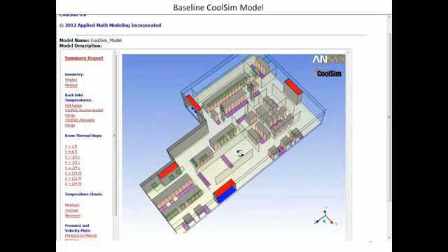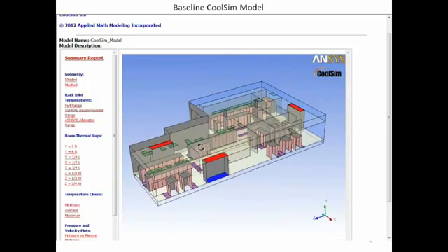Now at first thought you say, well, I've got maybe 20 tons of cooling in the room, that should be sufficient. I don't need it all, so it won't reject it all, and that is true. It rejects only what it needs. But what happens is the fans are running, in this case, full tilt. These are DX-based units, so they run with their fans fully on, which means you have a tremendous amount of airflow going on that's not needed and a wasted energy. So let's take a look.